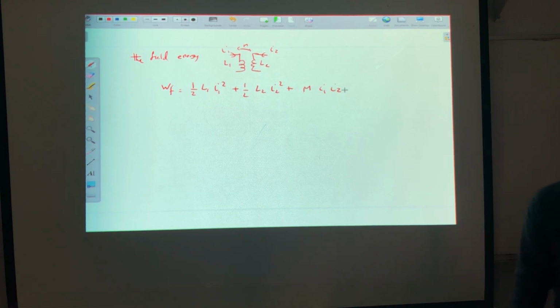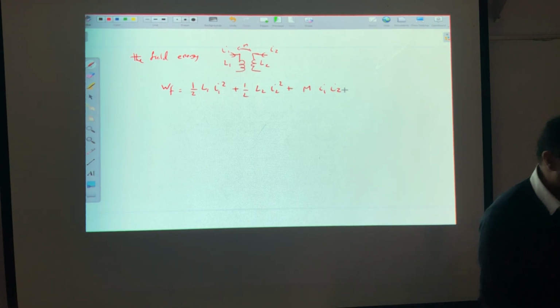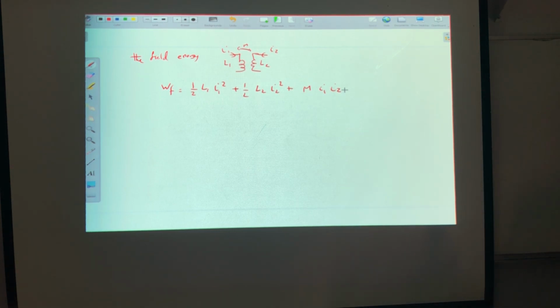Instead of that, I'm having a set of coils on the stator and a set of coils on the rotor. Correct? So who can give me the field energy in the machine? So you say that omega. Now this one, assume it is the stator. So you will say that this one will equal I ABCS transpose, LS, I ABCS.